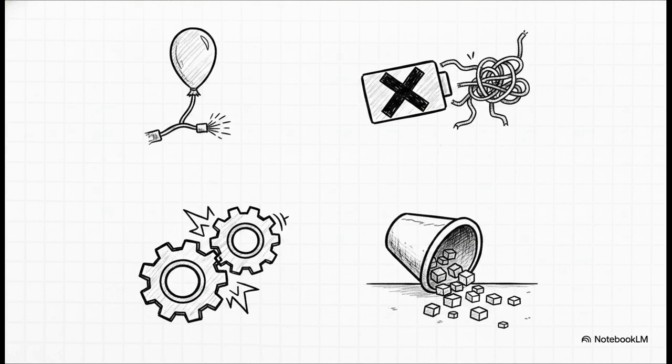Now, what's really interesting about these failure patterns is that the specific hexadecimal values actually translate directly to physical fixes. If you're reading all FFs, you likely have a floating MISO line, the wrong chip select, or the peripheral just isn't powered on to drive the output. If you read all 00, well, check your power state, look for a held reset pin, or honestly just bad wiring. If your bits are shifted by just one position, yep, you have that CPHA or CPOL mode mismatch we talked about earlier. And if the very first transfer passes, but later ones fail, you're probably looking at a startup delay issue or a stale FIFO buffer.